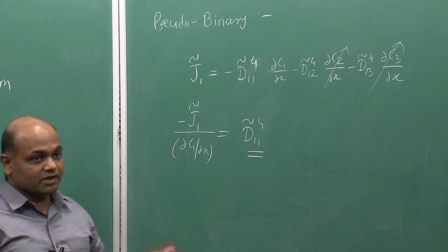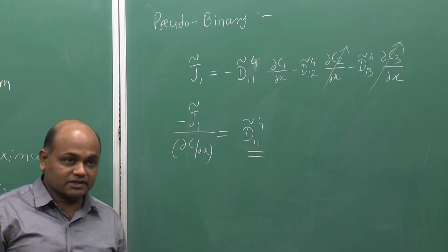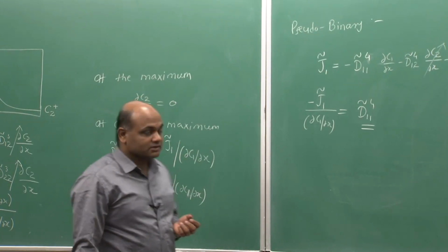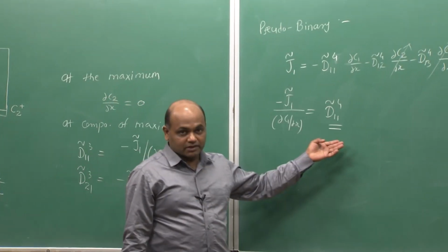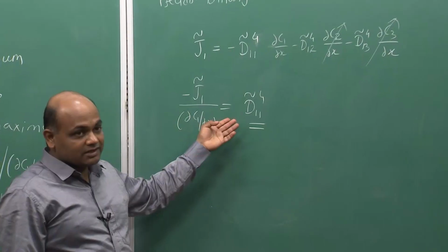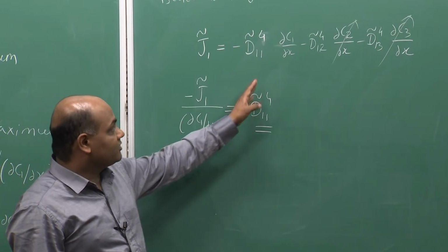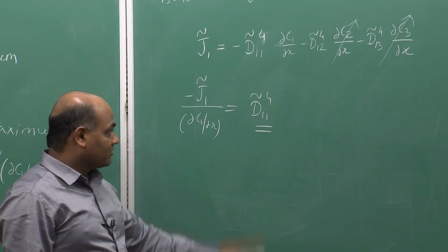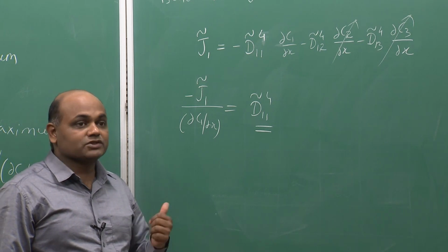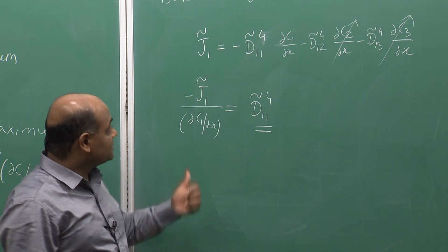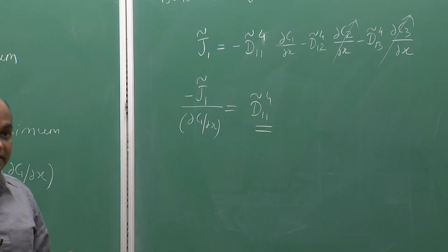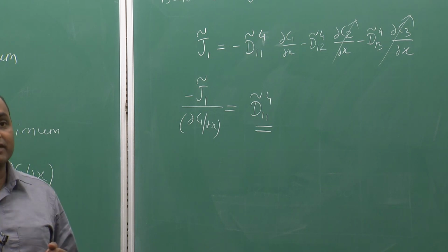So, of course, it will not give the entire set, but it gives an idea about at least how fast or slow a particular component is diffusing based upon its main interdiffusion coefficients. We can design such couples to get different main coefficients, and we can find out the main coefficients at different compositions based upon the pseudo binary technique. The advantage is this can be applied to any component system as long as only 2 components develop the composition